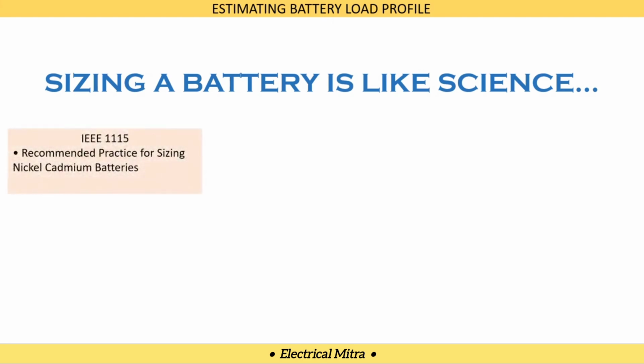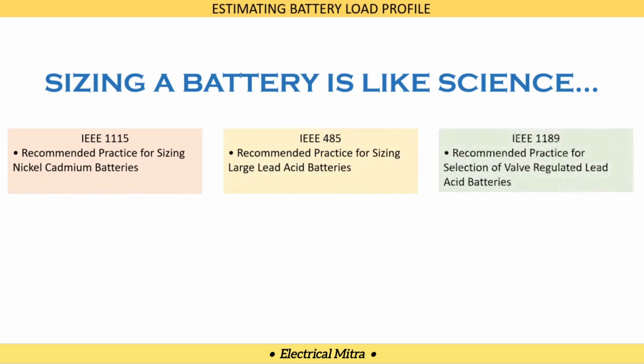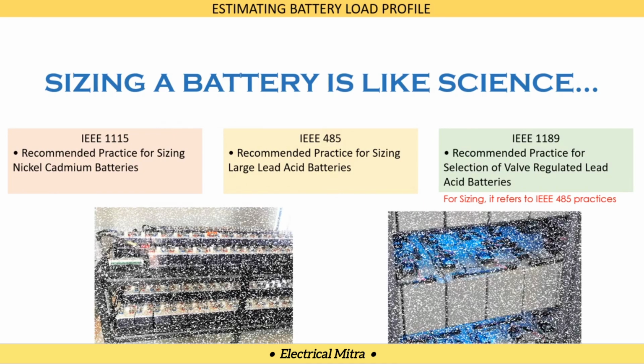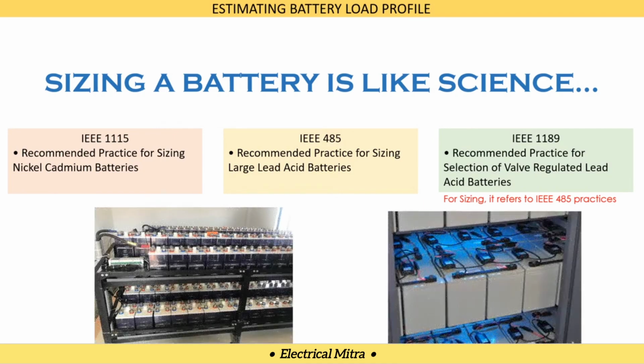IEEE 1115 provides the recommended practice for sizing of nickel cadmium batteries. IEEE 485 provides the recommended practice for sizing large lead acid batteries, whereas IEEE 1189 provides the recommended practice for selection of valve regulated lead acid batteries.